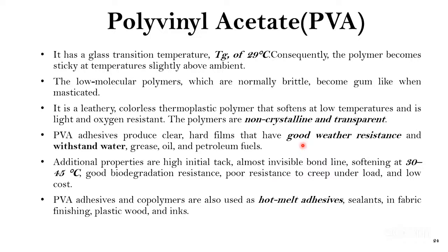Due to that reason, you will find that mechanical properties might be affected. This is a very general observation: if a very highly amorphous character is present in a particular polymer, then the mechanical properties, like creep resistance and strength, might be affected.